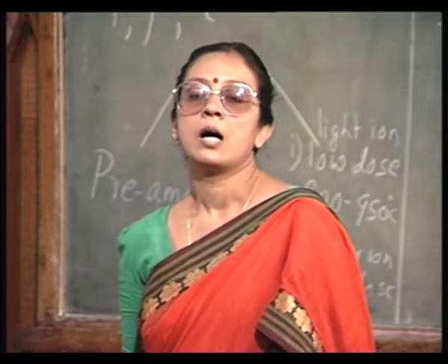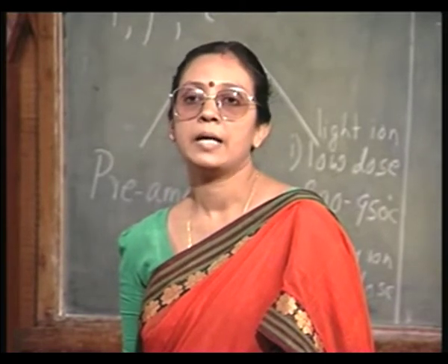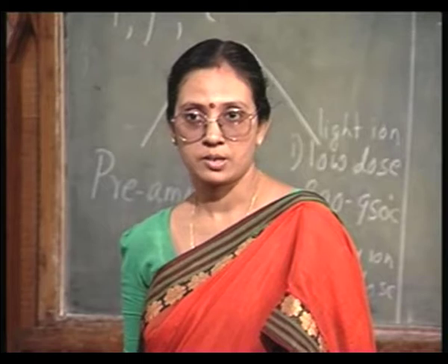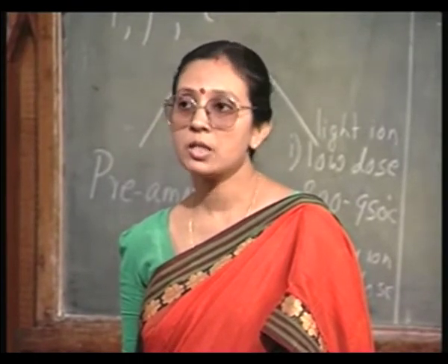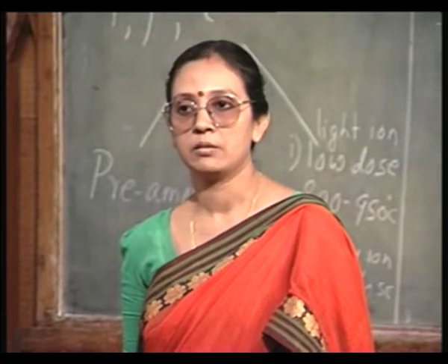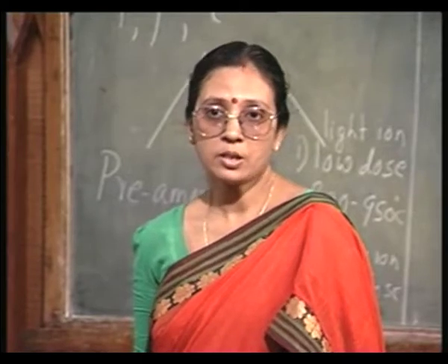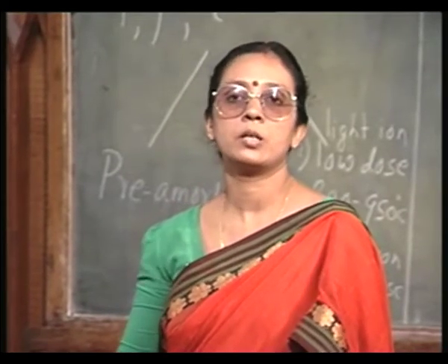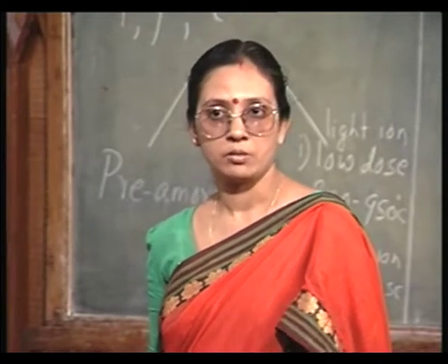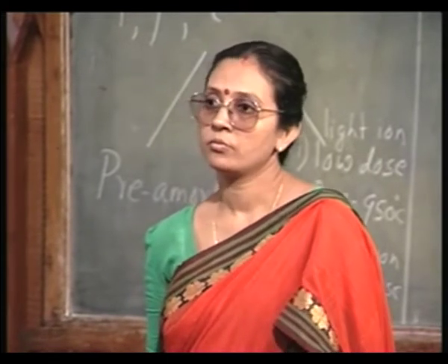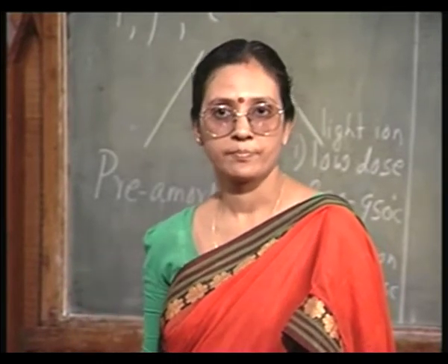Nowadays, after implantation, annealing is done by rapid processes. The annealing process we have discussed so far is actually conventional furnace annealing. That is, you subject the samples to high temperature for a given amount of time, say 20 or 30 minutes, at different temperatures.